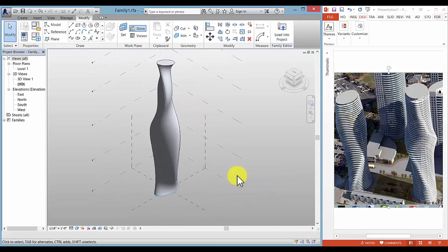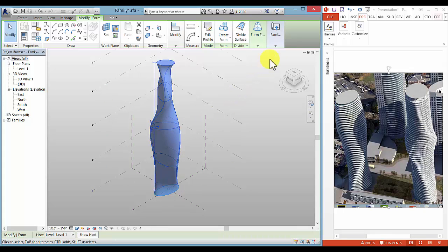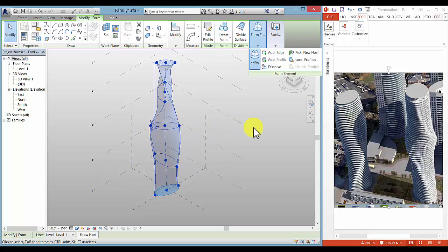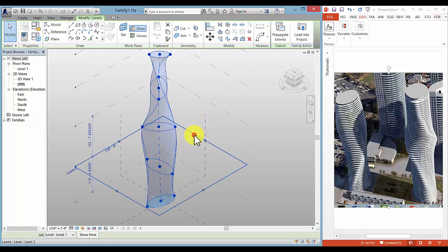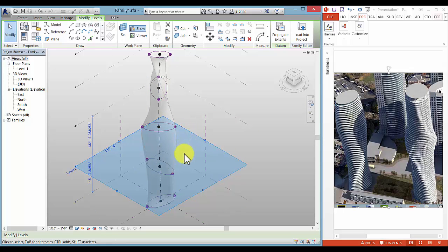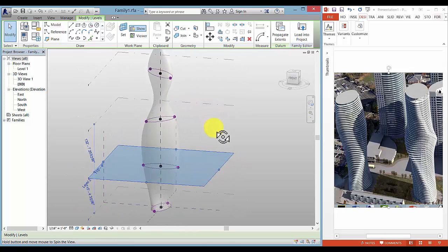If you click out in space and put your pointer close to the tower, you can select here the Tab key so that you can grab the mass and click on it, and then pick X-Ray so that we can kind of see through it. At that point, you're able to see where these different profiles are. They kind of come through the building there. Okay?